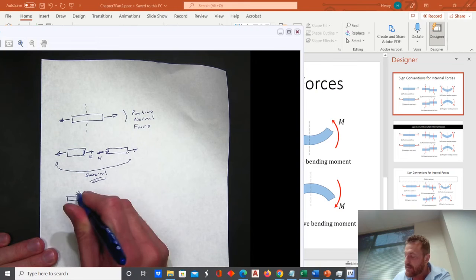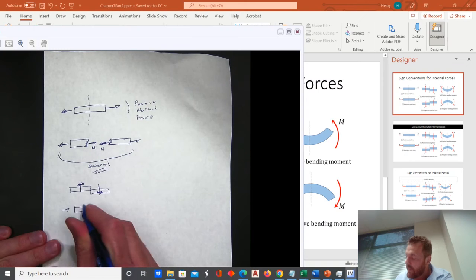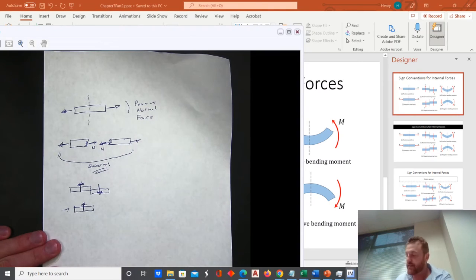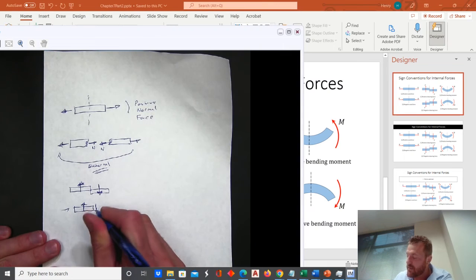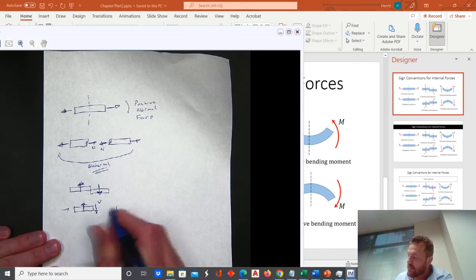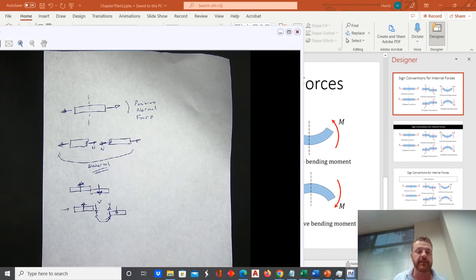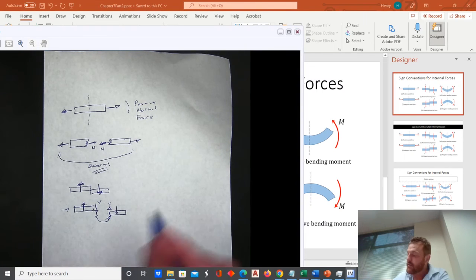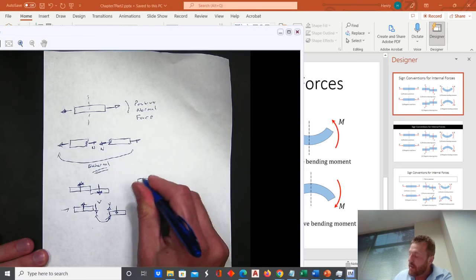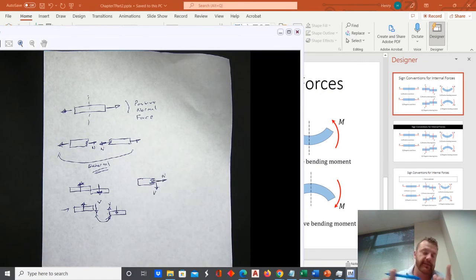If I have a force system that tends to induce this type of shearing stress, what I notice is that if I segment my body, since the external force is pushing this left portion up, the internal shear must be going down. And same idea vice versa: if on the right side this is going down, then the internal must be going up. Notice that these are also Newton's third law reaction pairs, which explains why they're equal and opposite. So if we have a segmentation of a beam and we're trying to calculate the internal forces, we assume that the normal force went to the right and the shearing force went down. Note that some books call the normal force the axial force, as you see in this case.